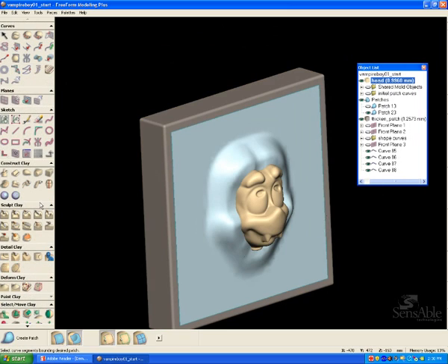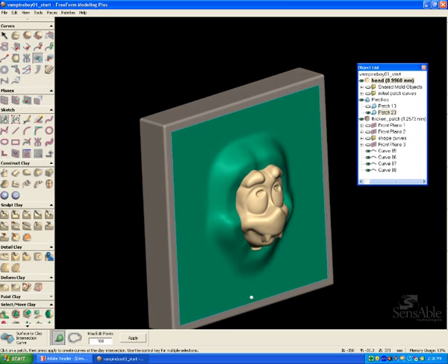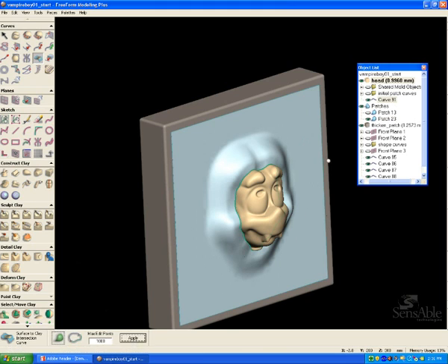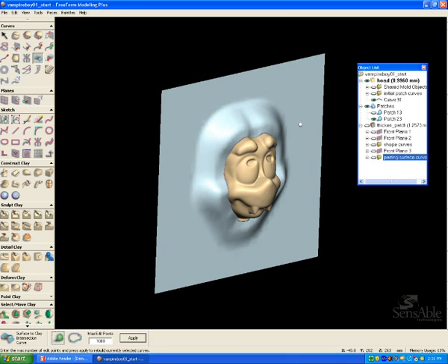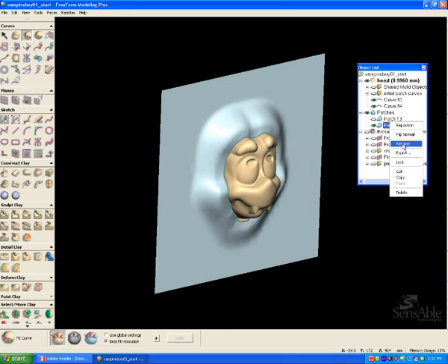So now you can see I have my complex patch, and what I'm doing now is I'm splitting the patch with the clay. So this is a surface to clay intersection, and it gives me a curve, and what this curve is now essentially is my new parting line.